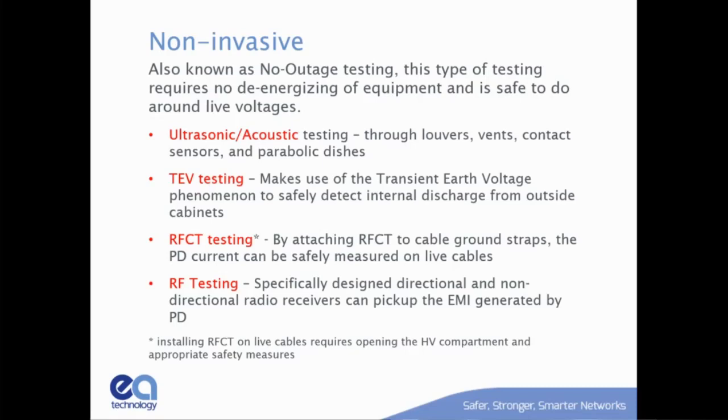You might get some old-time customers that say, I don't want to do PD testing because they did that once and it blew up a cable. And that was back before we understood that you shouldn't do really high voltage tests on cables with DC, with XLPE. And they had a lot of failures on high pot, really.